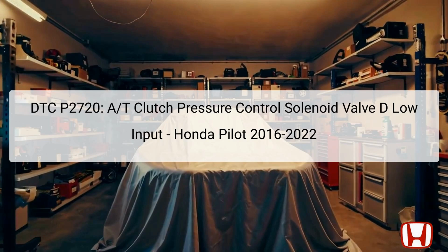The Diagnostic Trouble Code, DTC P2720, refers to a low input signal in the automatic transmission, AT, clutch pressure control solenoid valve D. This solenoid plays a critical role in regulating pressure to ensure proper shifting of gears within the transmission. If this solenoid does not receive adequate electrical input, it can prevent the transmission from shifting into second or fifth gear as part of a fail-safe function, causing potential driving issues.